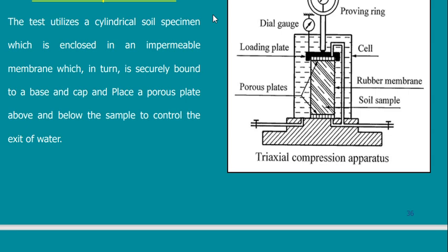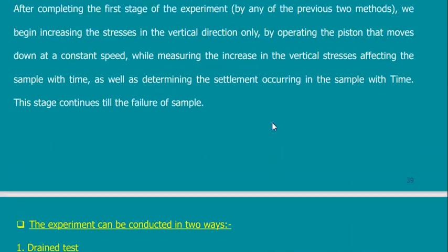But this pressure has to be from all directions, because I want the pressure not to exert any shear. I want it only to increase my normal stresses. So when I have pressure on my sample, then the sample can carry more. This is how you will find this.